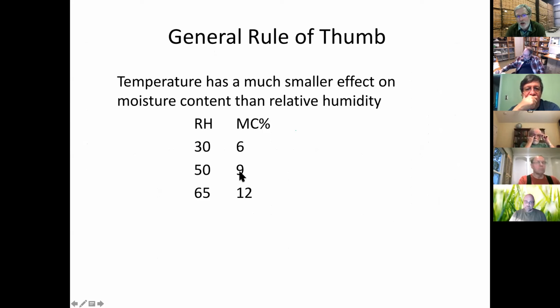And so if you know, hey, less than 30% relative humidity, it's going to be kind of dry. My wood's going to be shrinking. And if it's 50% and going higher, my wood's going to start swelling, I might want to take some measurements. So if you can just remember those four numbers, it'll really help you out. And that's when you know you're headed towards a potential problem.